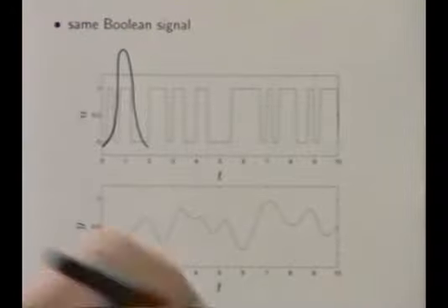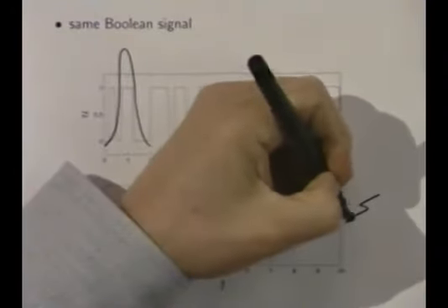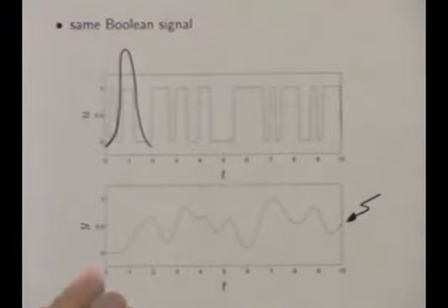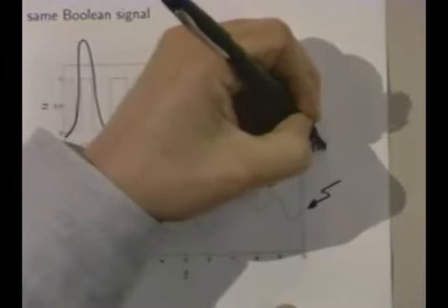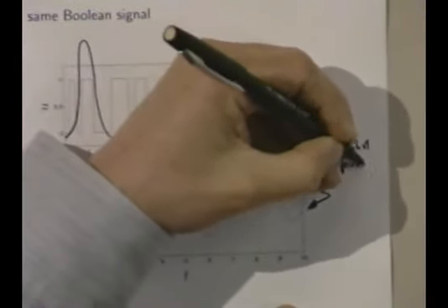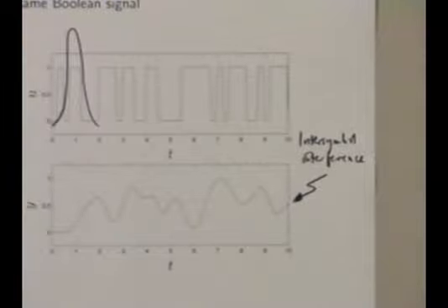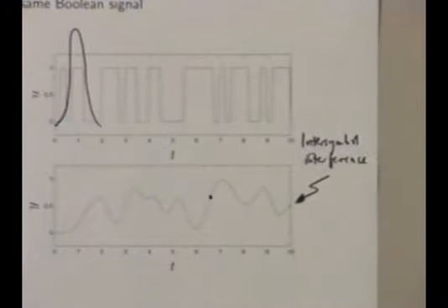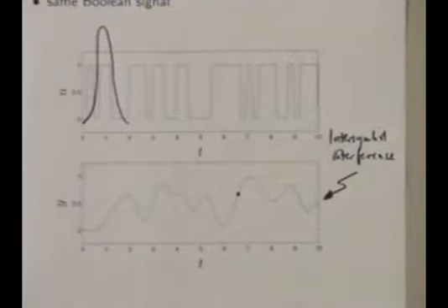Now, just for fun, I'll tell you what this is called. When this occurs, it's called intersymbol interference. You don't need to know it, but you will later. I think it's clear what's going on here. When you look at a certain output here, you're getting a contribution not just from the 1 or 0 that was transmitted then, but in fact from a whole bunch of other symbols. And it's very common when someone talks about ISI, intersymbol interference, for someone to ask, how bad is the ISI, or how long is the ISI?